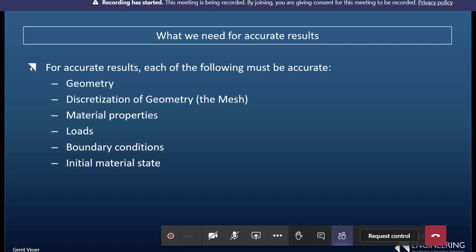In those cases, we need to find out what that initial stress state is. The load history also plays a significant role, especially if there was plasticity involved in some of the load cases or load steps in between. It kind of relates to the initial material state, except it builds on that and then takes the model further. So there's additional plasticity or whatever in the model.